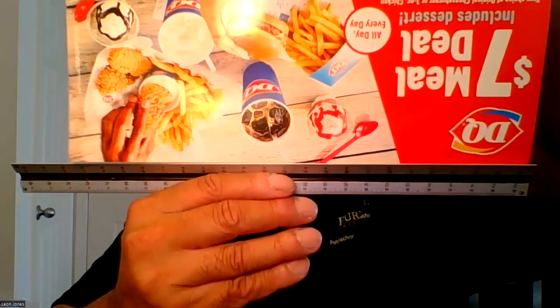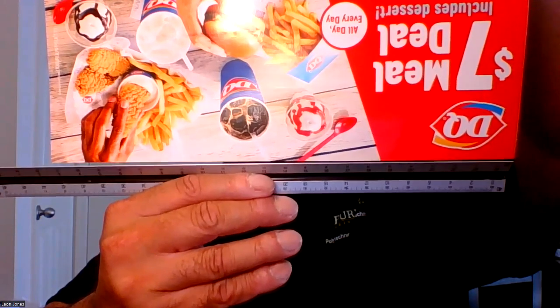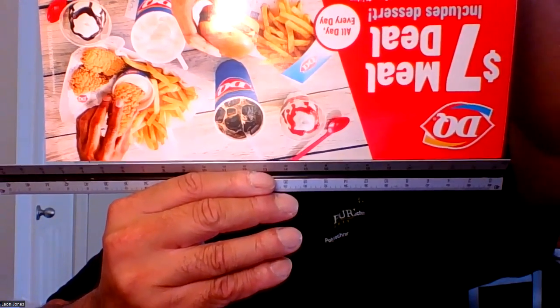And this paper, measuring it, I would get 50 feet, be 400 feet. Why? Because I have 8 inches, and 1 inch equals 50 feet. So 50 times 8 is 400 feet. That's if I was using this paper as a plan. That's the scale. Now, another scale that